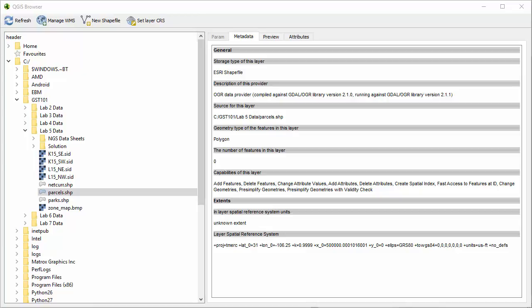Now that you've created an empty shapefile to store the digitized information, you will perform a coordinate transformation, also known as georeferencing, on the source data set so that it's in an Earth-based coordinate system. To perform this task, you will be using a plugin. Plugins are small add-ons into QGIS. Some are created by the core QGIS development team, and others are created by third-party developers.